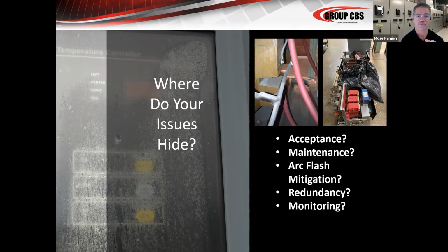And if you have a breaker that's not operating properly because of lubrication, that is one of those Band-Aid situations I mentioned. That's fixing the symptom. It'll get your breaker working again. It'll get it operating properly, yes. But in a month, 6 months, a year, you're going to be right back where you were with this breaker, because that's going to evaporate. It's going to go away. And you're also washing out whatever remaining grease was in there when the breaker was first built. So we have to be really careful.